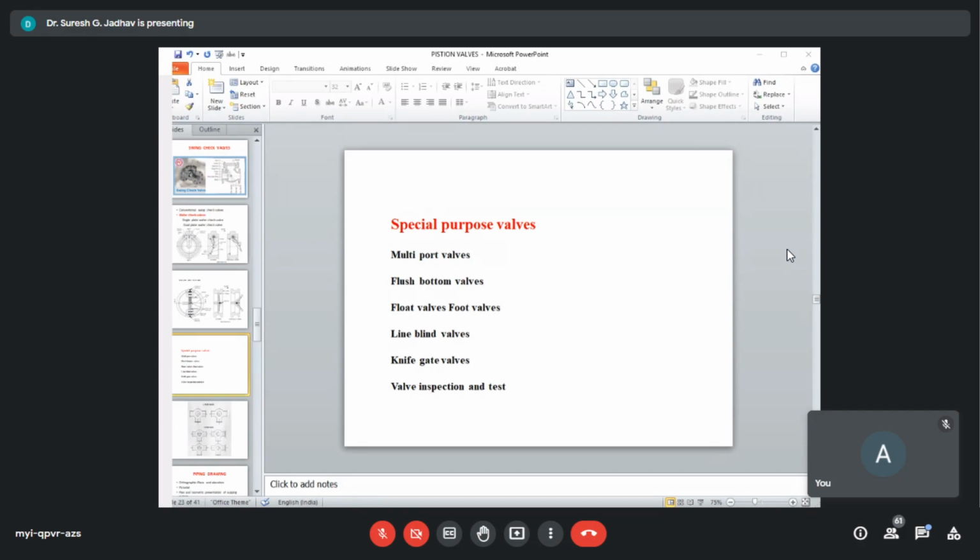The shut-off is achieved by seating the disc against the body seat. The disc could be globe type or ram type. Jacketed flush bottom valves are also possible if required for the services. The disc and seat could also be machined to such accuracy to serve vacuum duty as well.